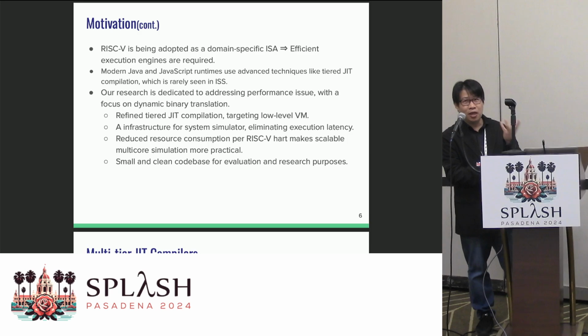We adapt the idea of tier JIT compilation into the low-level virtual machine, in particular RISC-V instruction set simulation, and we want to ensure that the simulator itself always consumes fewer system resources.